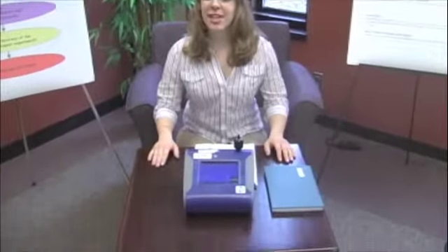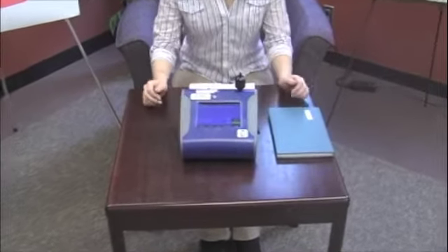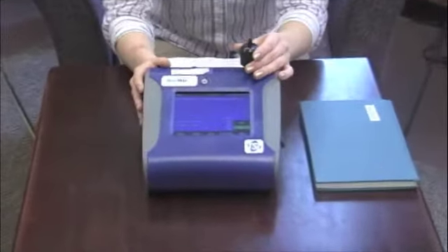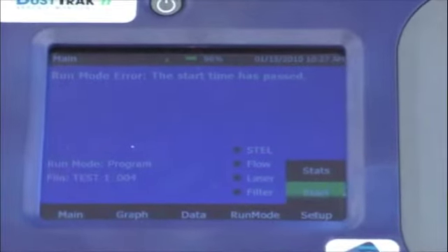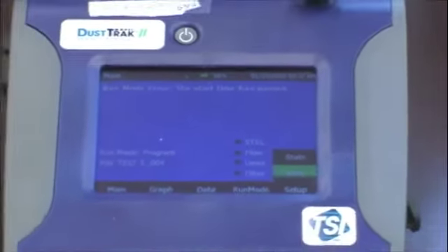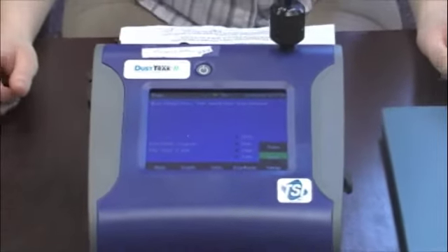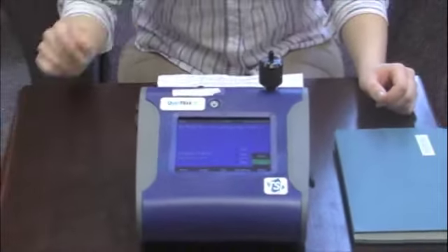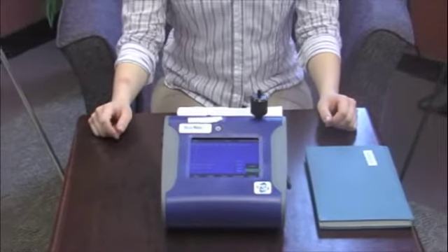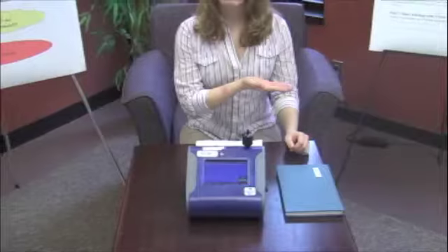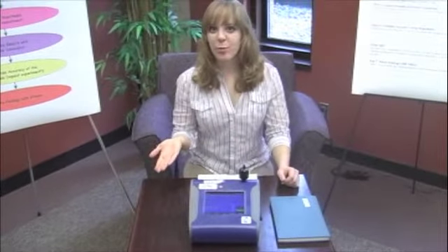The air quality data that I gathered, and that I'll be sharing with you, was collected using the DustTrak aerosol monitor. The DustTrak is a real-time portable particulate matter concentration monitor, which measures particulate matter in micrograms per cubic meter. The DustTrak pulls in air through a small nozzle and then records the concentration of the particulates. The monitor has logging capabilities, and its calculations are a reliable exposure assessment of the particulate matter concentrations corresponding to respirable sizes of 10, 2.5, and 1.0 microns, or PM10, PM2.5, and PM1.0.